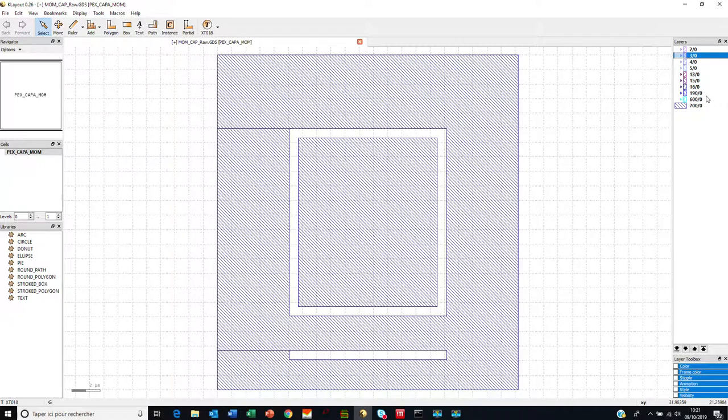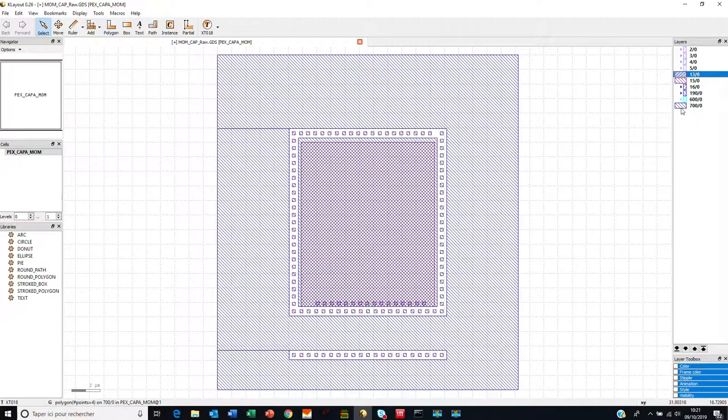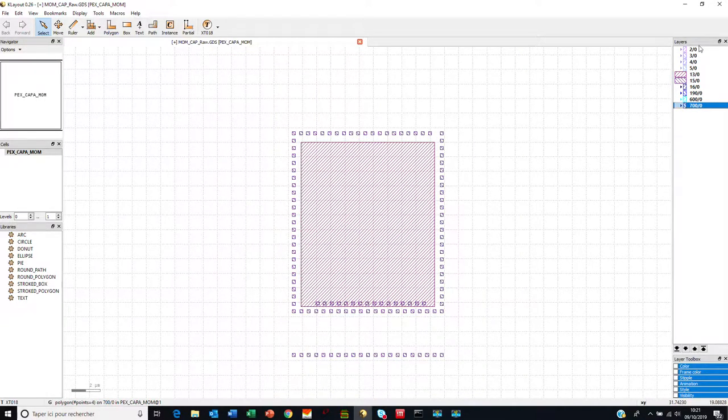Now if we go a bit further and look at layer contact, which is layer number 15, we notice that we have contacts on active diffusion, and we have contacts in places where no active exists. In fact, at this place we have poly, if we hide the STI. So we have contacts on active and contacts on poly, and both types of contacts lie in the same layer.